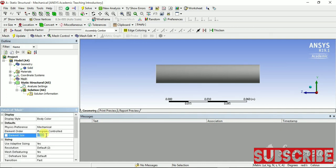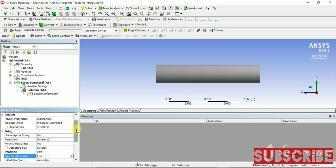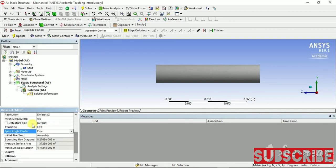For example, I took it as 0.002 meter, that is 2 mm. Then the sizing option is present there. In the span angle center, if you want to get a very fine result or very good result, you should use the fine option. It is a very complex process.